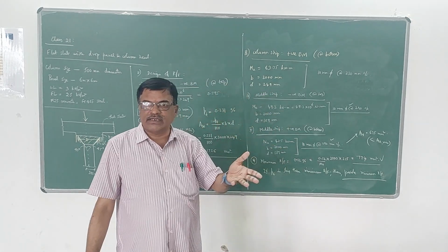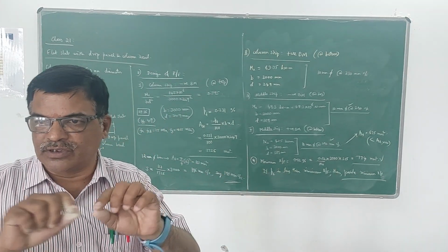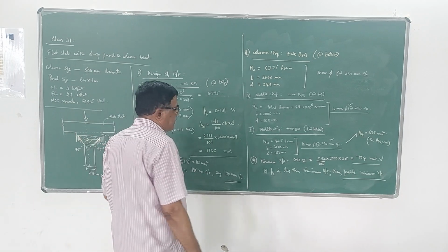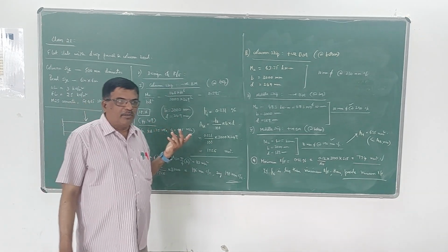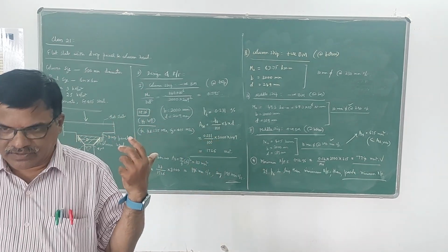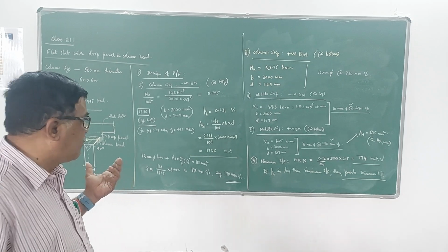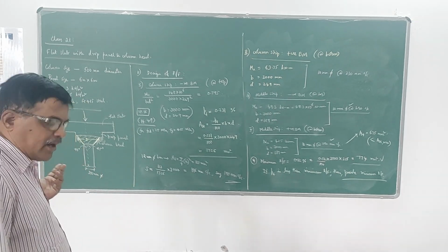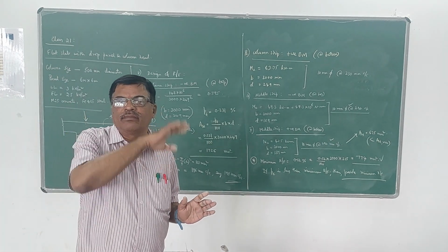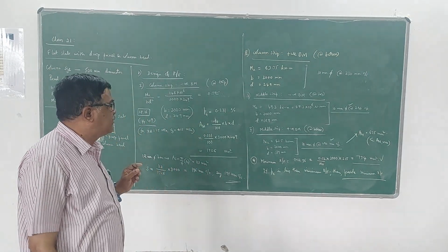If they ask you the sketch, I have already posted that sketch. So just you have to show some lines. So please note that in a flat slab, whether they give drop or both drop and column head, the design procedure remains the same. Only thing is, if they ask you to provide a column drop, then additionally we have to check for punching shear by taking into account the column head diameter. That's all. So this is how the flat slab is designed.